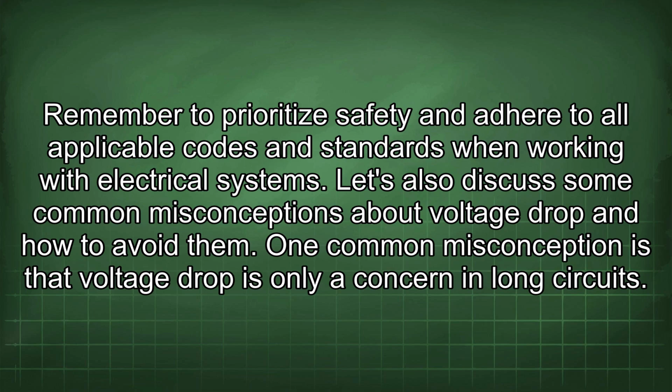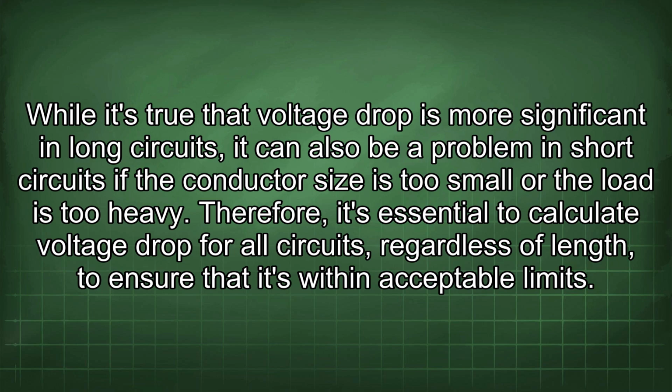One common misconception is that voltage drop is only a concern in long circuits. While it's true that voltage drop is more significant in long circuits, it can also be a problem in short circuits if the conductor size is too small or the load is too heavy. Therefore, it's essential to calculate voltage drop for all circuits, regardless of length, to ensure that it's within acceptable limits.